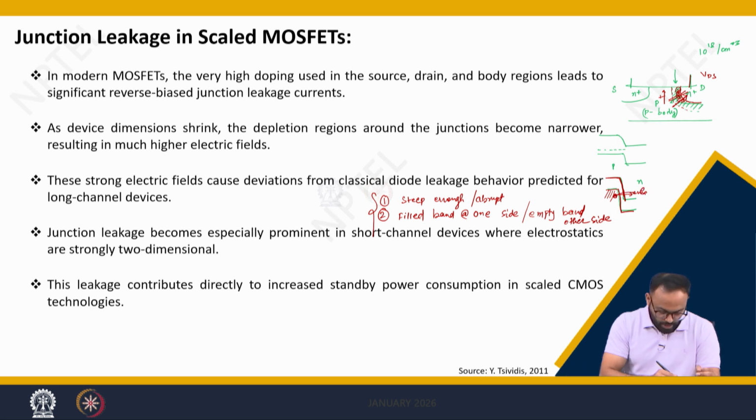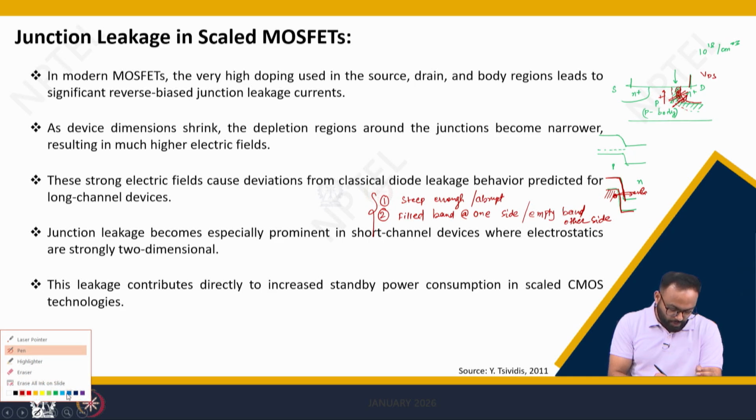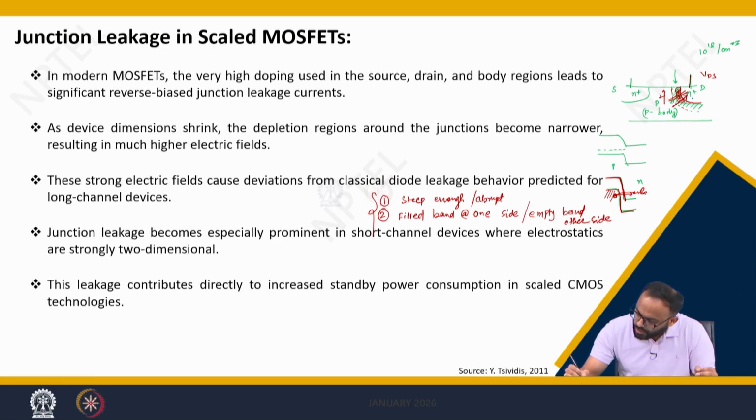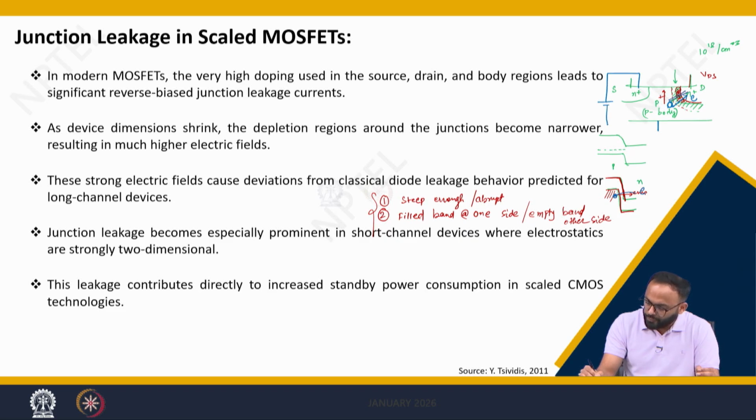The newly tunneled electron will reach the drain, and similarly the hole is created because of the tunneling of the electron. Now, you have a body connection which is either negative or 0. If you connect VSB, it is negative. So, this hole will give you what?